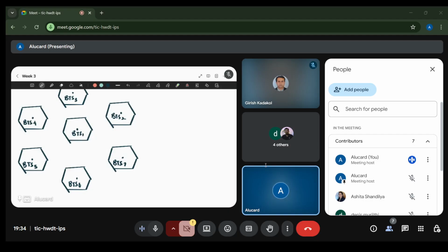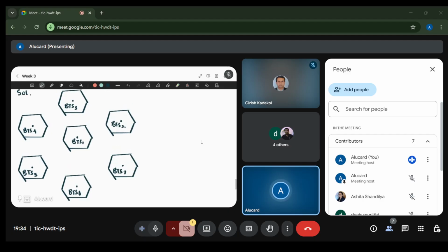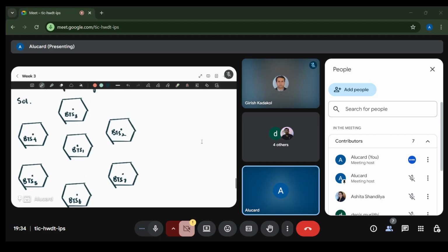Now, what you do is suppose some frequency band is given to each of the cells. So all of the co-channel cells use the same frequency band. You split that into three separate bands, F1, F2, F3, and you say to serve users in this part of the hexagon, I will only use channels in the F1 band.